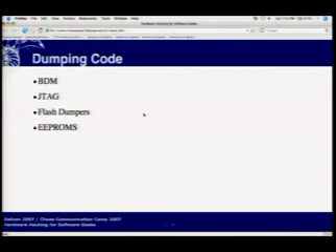Some BDM systems also let you do things like clock stepping to slow down the process and inspect each register as each clock cycle passes, but also modifying registers and modifying memory locations. These actually have a BDM port on the back. As you see, I put a pin header on it. It's actually a one-wire bus that allows you to debug the chip.